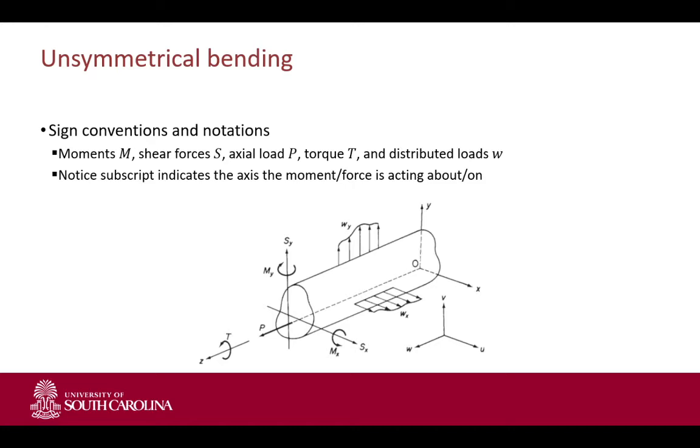Because if you look at the lecture slides, you would think, so Mx here follows the right-hand rule by pointing your thumb in the positive x direction. Z follows the same rule, and My doesn't. Okay. And then if you look back on our example, the moment was applied in such a way that Mx was basically in the opposite direction, so therefore we had a negative moment.